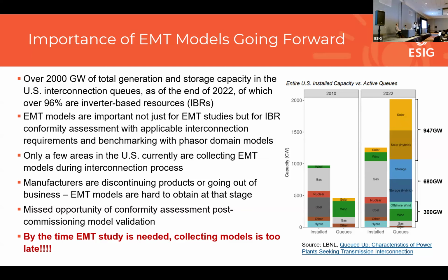One other thing, even if you look at areas that are already collecting EMT models, you can see that sometimes they need to study an area where there are already older IBRs connected, and they're looking just at the new IBRs, but they cannot study it completely because they don't have models of the old inverter-based resources. And now as they're going back, trying to get these legacy models, the generator ownership has changed hands, so nobody actually knows what's in this plant anymore.